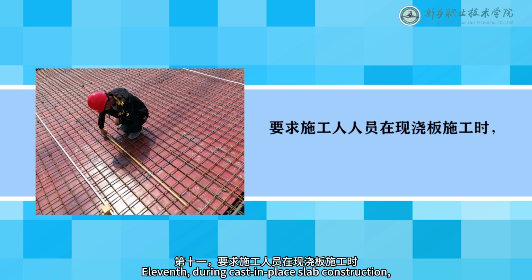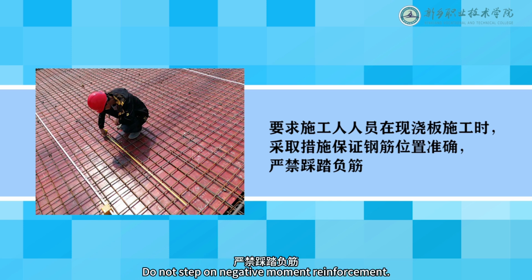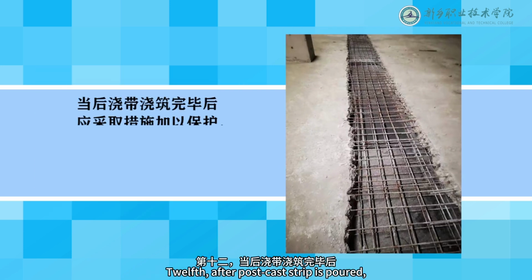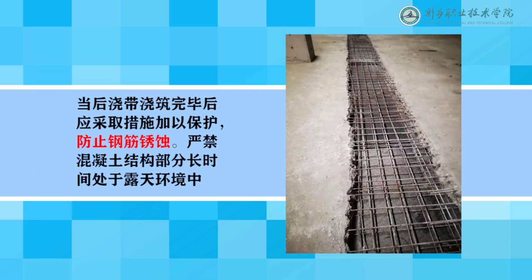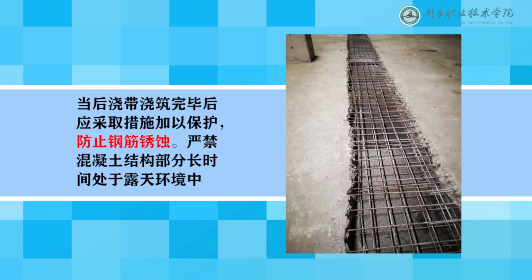11th, during cast-in-place slab construction, measures must be taken to ensure the correct positioning of reinforcement. Do not step on negative moment reinforcement. 12th, after the post-cast strip is poured, protective measures are required to prevent rebar corrosion. Do not leave concrete structures exposed to outdoor conditions for long periods.